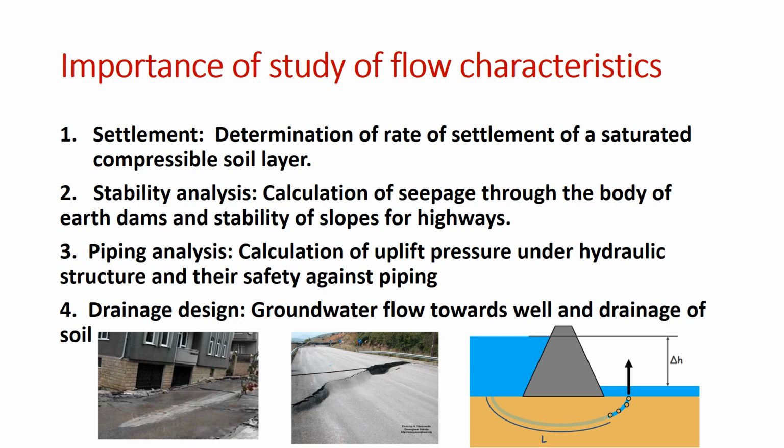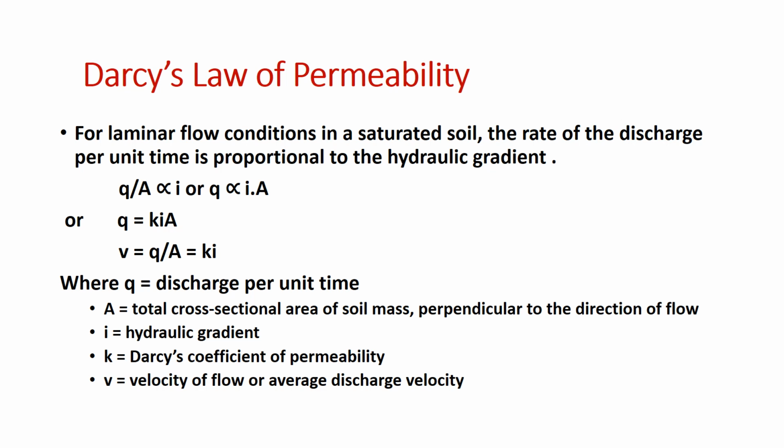Now, if we talk about the laws of permeability, Darcy's law of permeability is very important. And for laminar flow conditions, there are two things important here. For laminar flow in a saturated soil, the rate of discharge per unit time, suppose discharge is q, the rate of discharge will be q upon A, which is proportional to the hydraulic gradient.